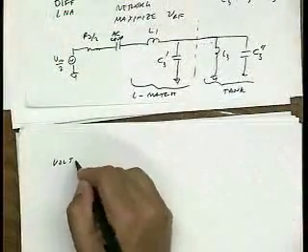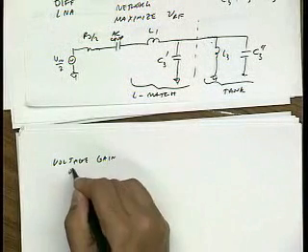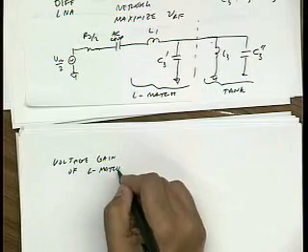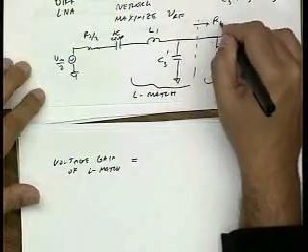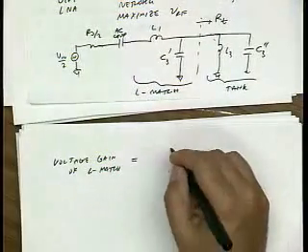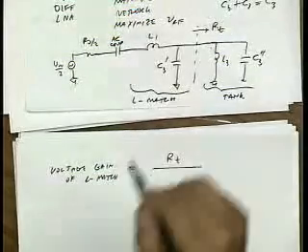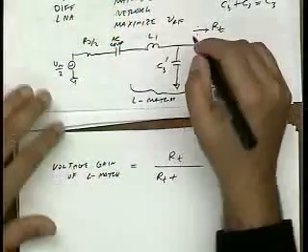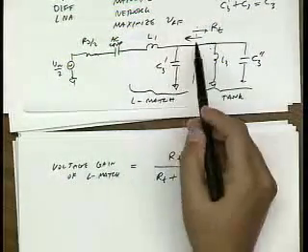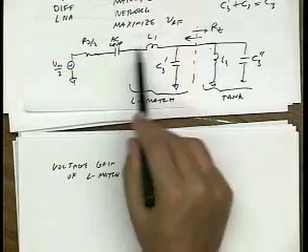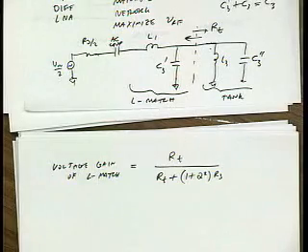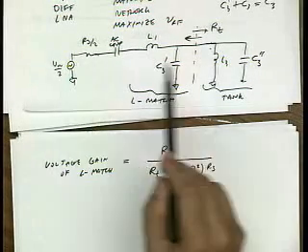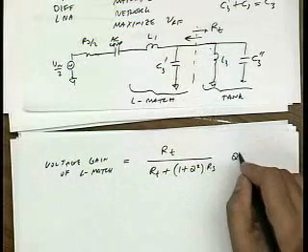So the voltage gain of this stage is equal to roughly, let's say that in resonance I see R tank looking to the right. I'm going to see R tank divided by R tank plus the source resistance. If I look back here, the source resistance is boosted by 1 plus Q squared because of this L matching network. And the voltage here is boosted up by effectively Q, or more exactly the square root of Q squared plus 1.